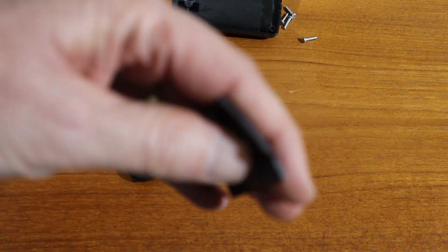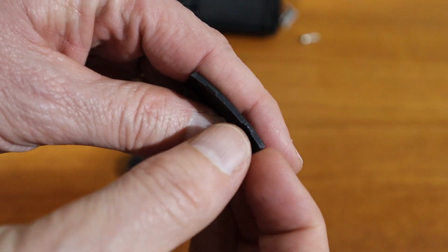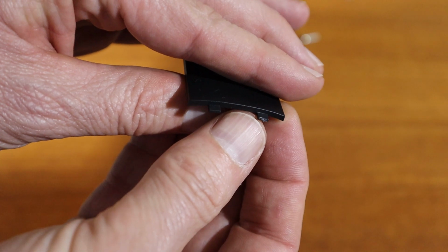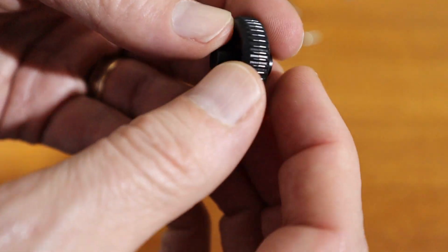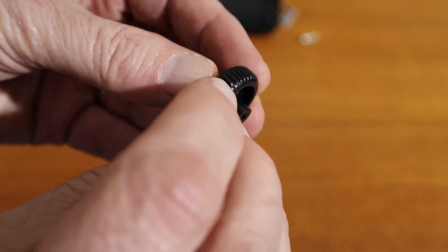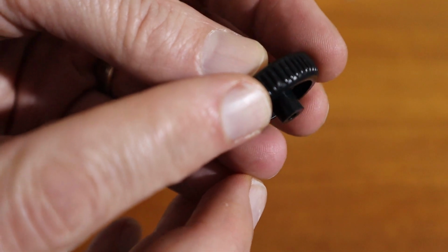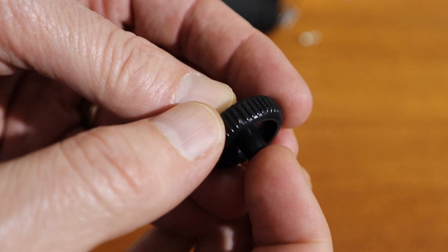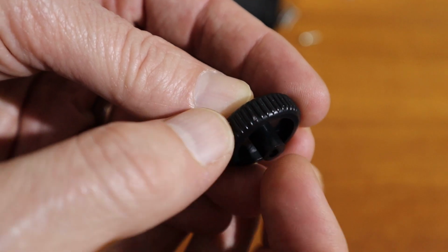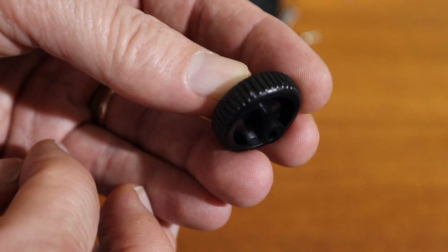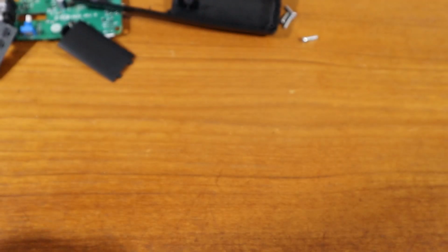If we look at the battery door, this is the location of the gate right here. Again, you can see that the plastic is a little bit white. And then if we look at the thumb wheel, let's see, where is it? There it is. So right there, see if I can focus this better. Right there is the place where the plastic is injected into the thumb wheel. So I think that's pretty amazing how that's all done.